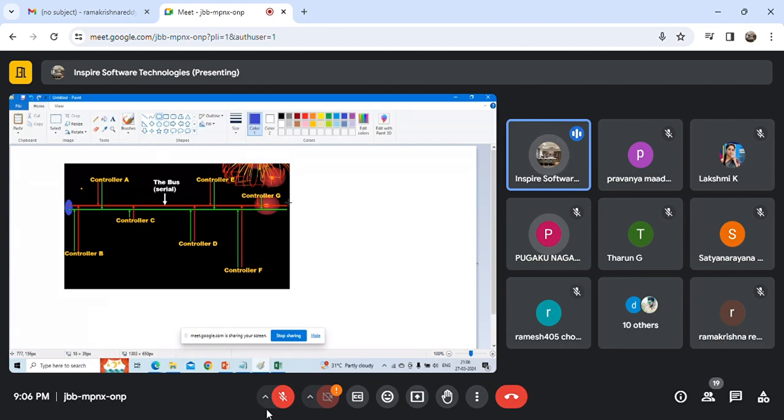That termination resistor is provided for maximum power transfer, an electrical concept. A 120 ohm termination resistor is generally used, and practically it can vary depending on the actual physical signal and controller. But 120 ohms is the standard resistor that we use here.